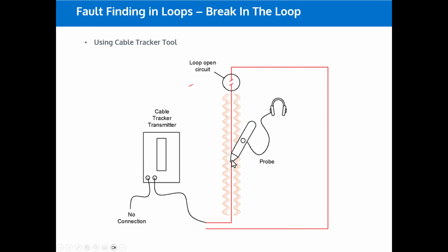In my experience, it's down to a resolution of about a millimeter either side. Again, this normally happens with copper tape that's been cut by carpet fitters, for example. On this side of the cut you hear the tone; on the other side you don't get anything, and that's how good the resolution is.